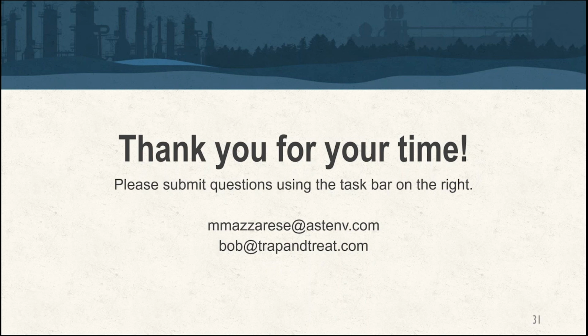Well, it's all going to depend on, number one, the mass flux coming through that cross section, right? So we've got a certain amount of, say, sulfate that we can load up into the barrier, which is going to be your long-term terminal electron acceptor. That is going to be utilized over time. You're also going to get that advected out of the PRB zone. That's going to be a function of the flow rate coming through that cross section.